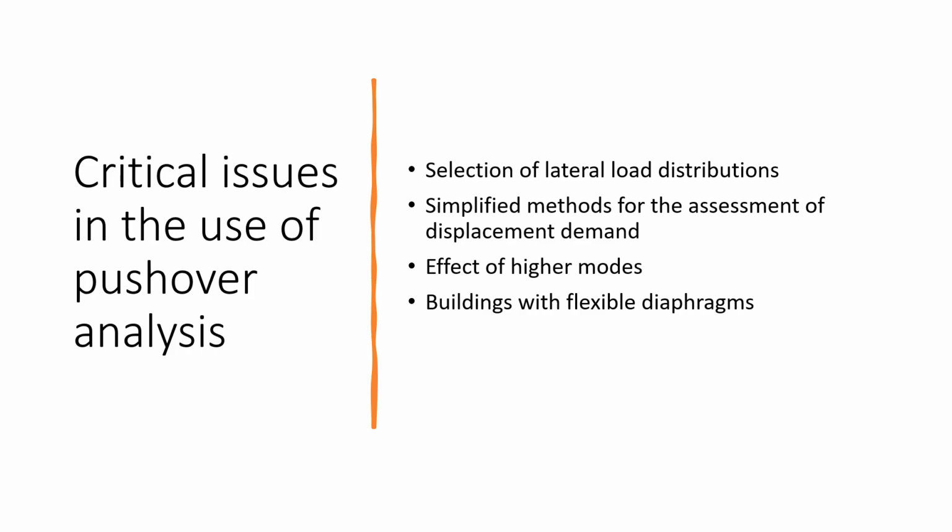We know that codes and tools provide the way of using pushover analysis in case of stiff diaphragms, semi-stiff diaphragms, or very, very flexible diaphragms, in which we are allowed to analyze single walls instead of them being part of a complete building model.